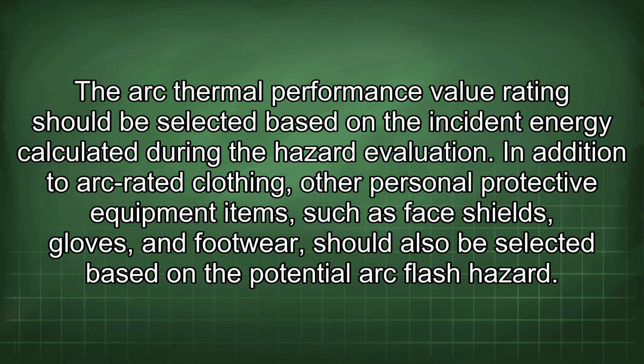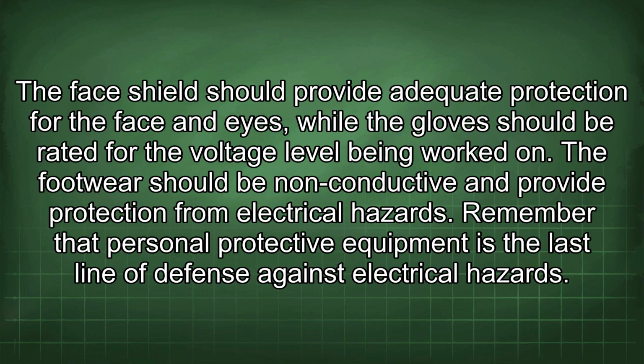In addition to arc-rated clothing, other personal protective equipment items such as face shields, gloves, and footwear should also be selected based on the potential arc flash hazard. The face shield should provide adequate protection for the face and eyes, while the gloves should be rated for the voltage level being worked on. The footwear should be non-conductive and provide protection from electrical hazards.